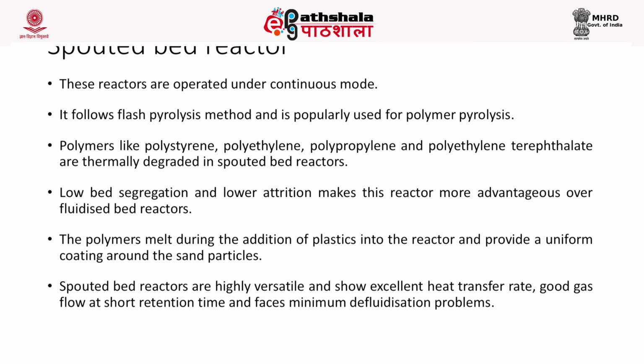Low bed segregation and low attrition makes this reactor more advantageous over the fluidized bed reactor. The polymers generally melt during the addition of plastics into the reactor and they provide a uniform coating around the sand particles. Spouted bed reactors are highly versatile and they show excellent heat transfer rate, good gas flow at a very short retention time and face minimum fluidization problems.